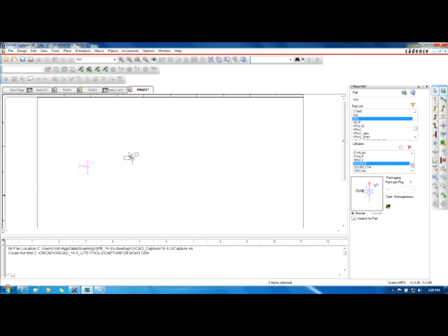But now you can go up here and hit the arrow, and it'll be off. Or to get this off once you're done using it, you can just say end mode. That was a right mouse click and then end mode. Okay, also escape. And the keyboard shortcuts are probably the best to use really if you're going to be doing this a lot.